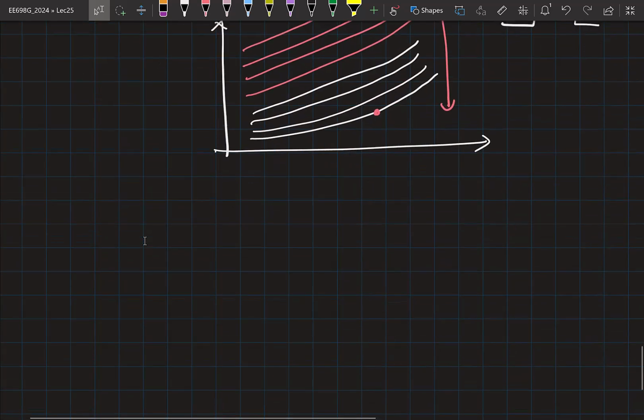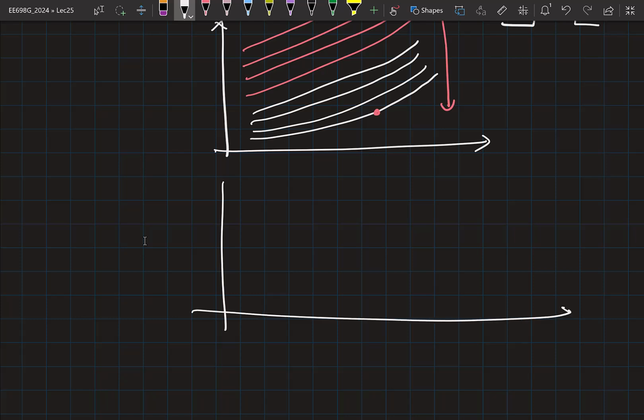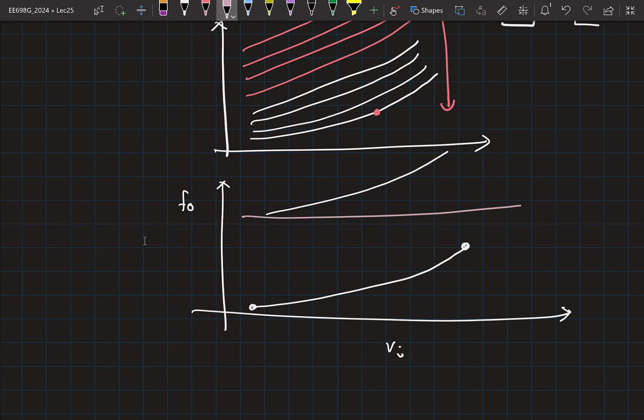So one more point about having these multiple bands is, you will have to make sure that there is no dead zone between the bands. So, for example, let's say this band covered from here to here. If the second curve was beginning, let's say from here, you have a region here which is not covered by either of the curves.